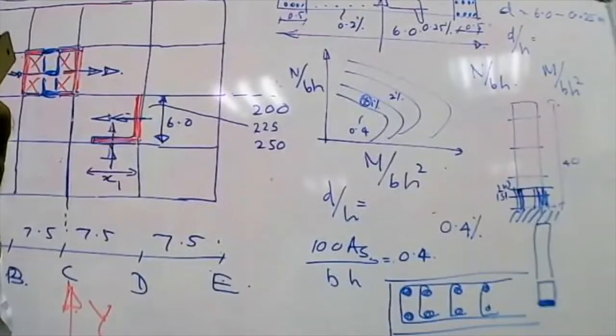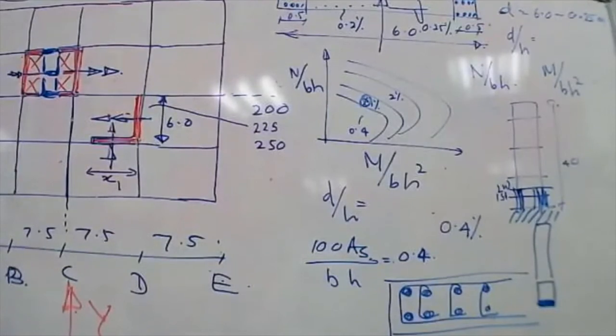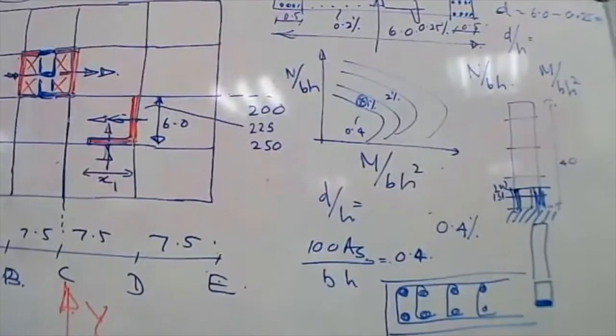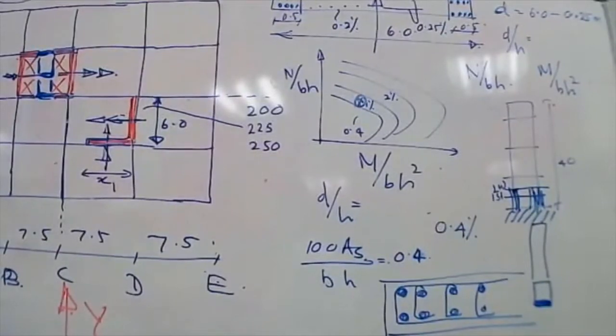There are a few. I will read them out. How do we select the depth of the wall sections at the two ends? And the other one, do we need to consider slenderness in these wall designs when designing as a column? Good questions, yes. Basically, it's a little bit of judgment, because you don't like too small and too big. So if it is 6 meters, you might consider even 0.75 meter or 0.8 meter ends rather than 0.5 meter ends.